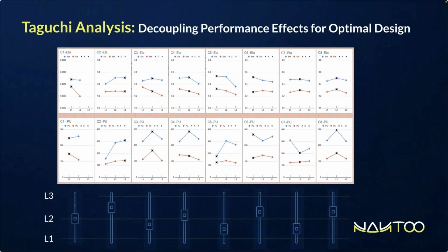So basically, each control factor is like a small slider, a small lever that we can use to tune or change the design of our machine. And we can set it up to 3 levels, from 1 to 3 levels each time. In this case, the return of the Taguchi analysis will give us the optimum configuration given those control factors and given that range of levels that we set.